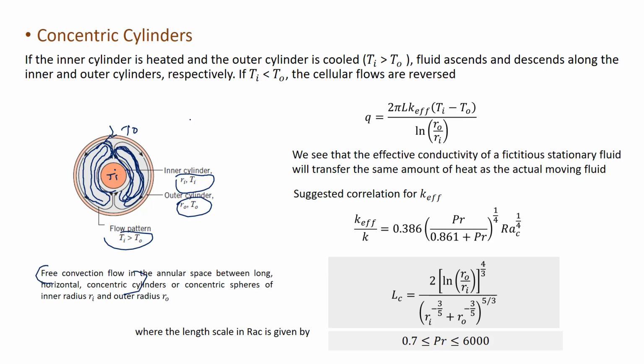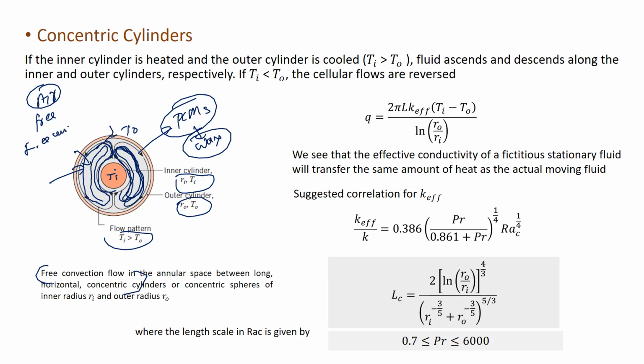You can see in the case of heat exchangers filled with PCMs, phase change material like wax, this kind of internal convection is happening. So don't think that it is only air that is responsible for free convection. In any fluid which is in the fluid state, free convection happens. The density should be driving the flow, then that is the condition.